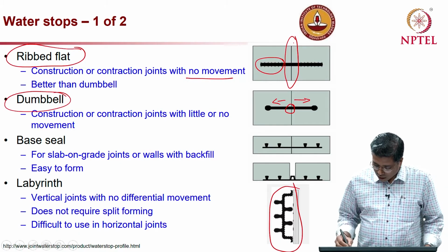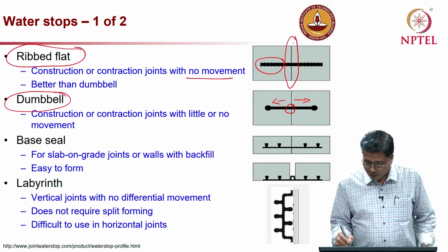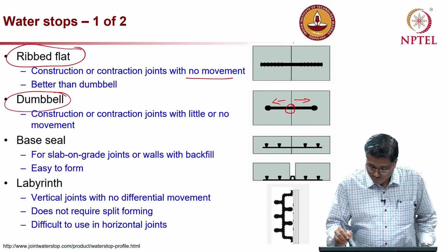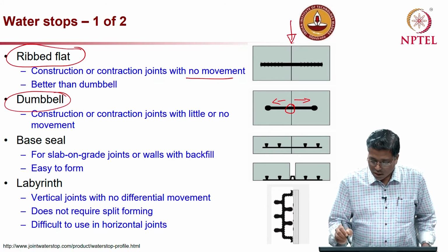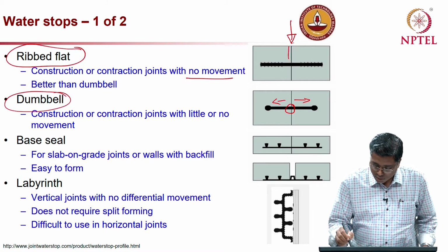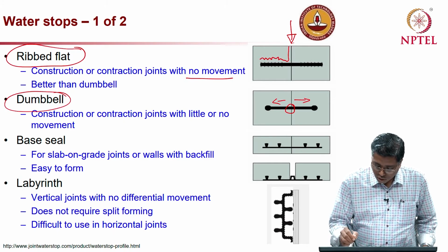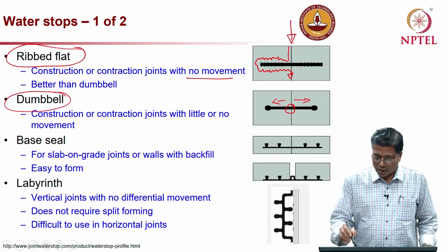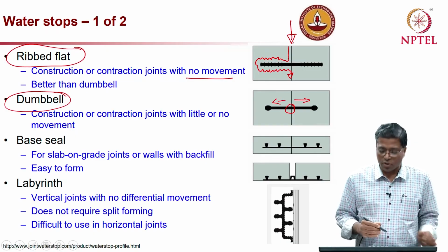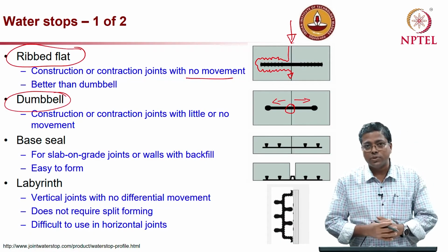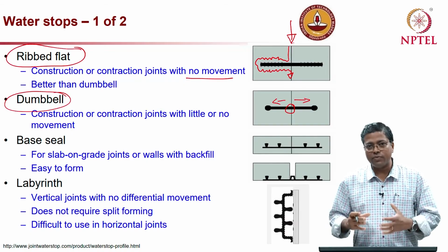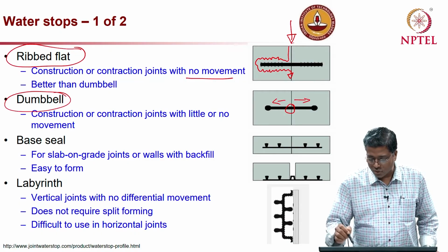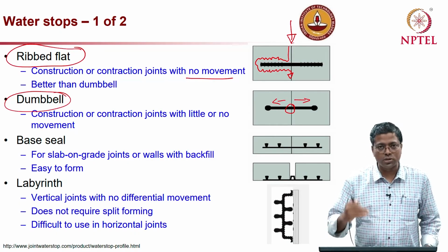You can see here how long. The idea here is, let me take this example of the first image here. If water is getting in through this, the water should come like this, it has to go all along and then go like this, then only it will reach the bottom. And this elongation or extended path for the water will itself stop the water from entering. So, it will be very difficult for water to go from one side to the other. In this drawing which I showed, from top to bottom, it will be very difficult. So, that stops the water.